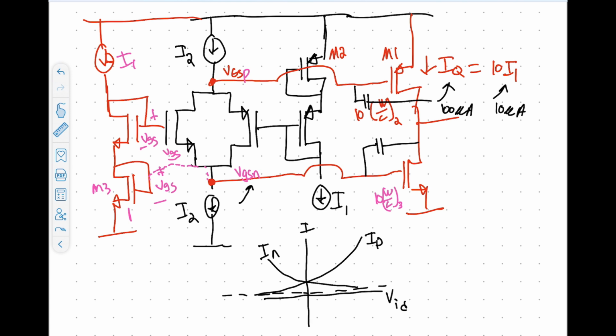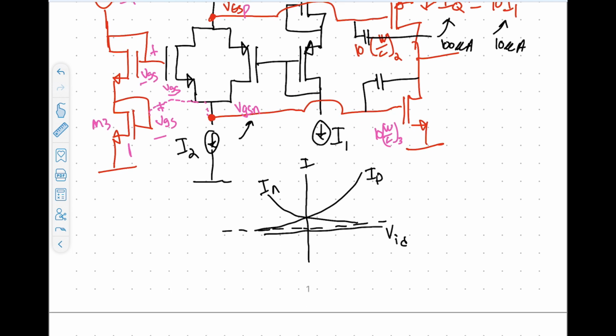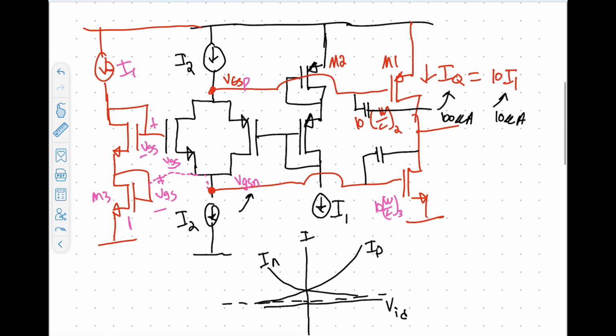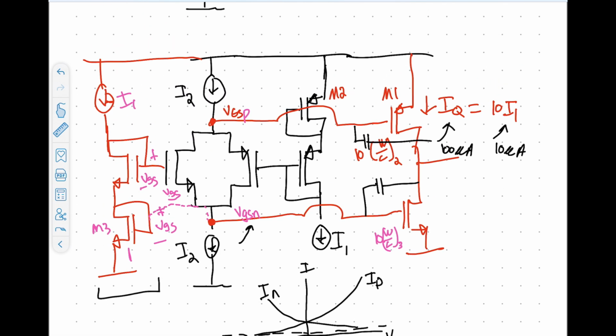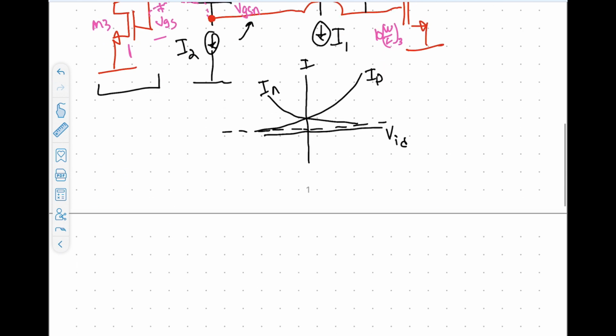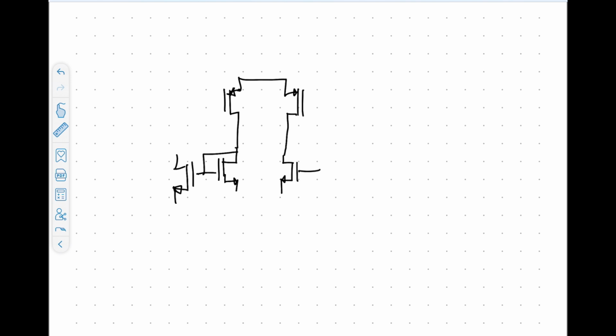Now, I want to show you one more thing. I want to actually insert this within an amplifier, so you have an idea of what that would look like. I'm not going to draw this bias structure or this other bias structure, because it's just going to clutter things up a little bit. But if we go back to an architecture that I really like, which is the current mirror OTA, I'm going to draw that real quick. So if we have a PFET input, such as this, okay. No surprises yet. All right. Okay. Now, up top we'll have the PFET mirror.